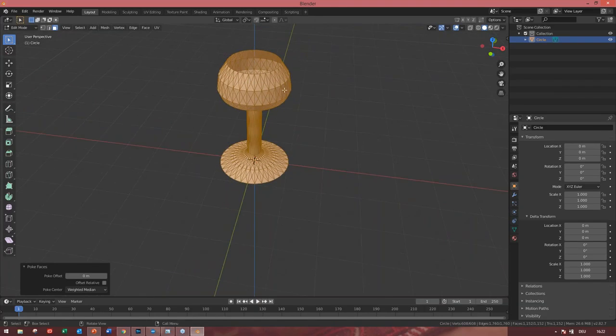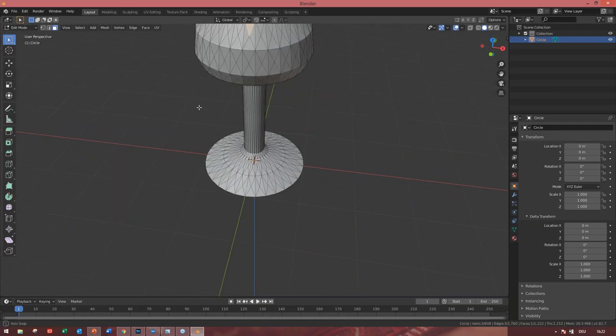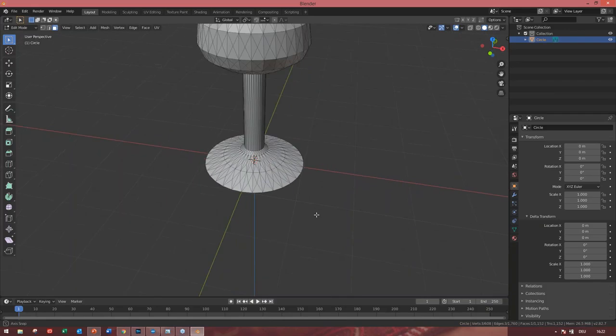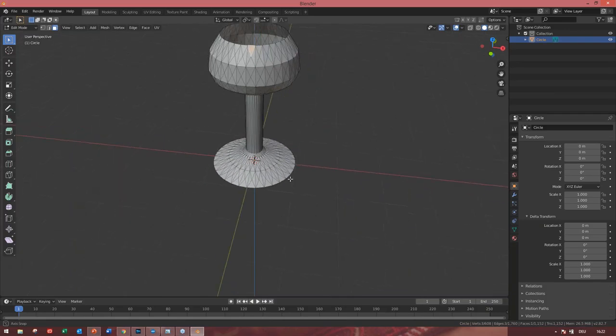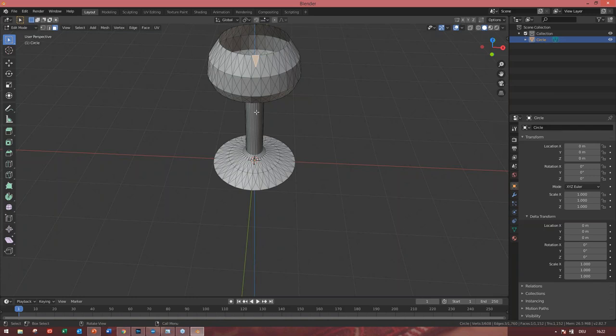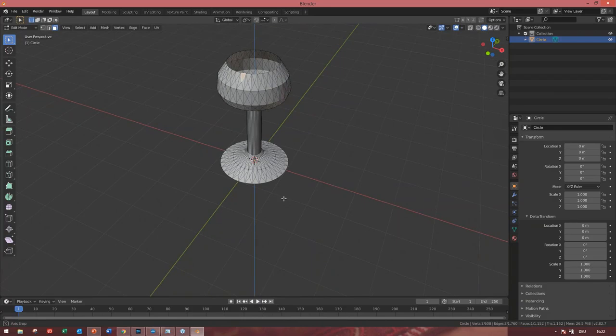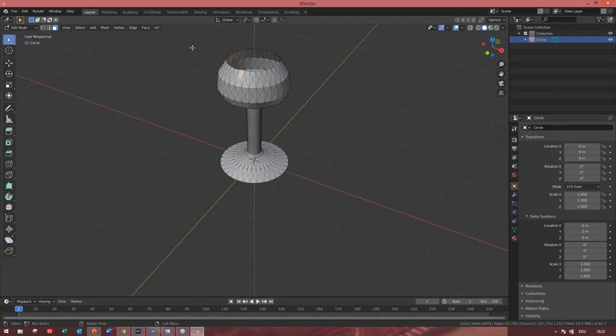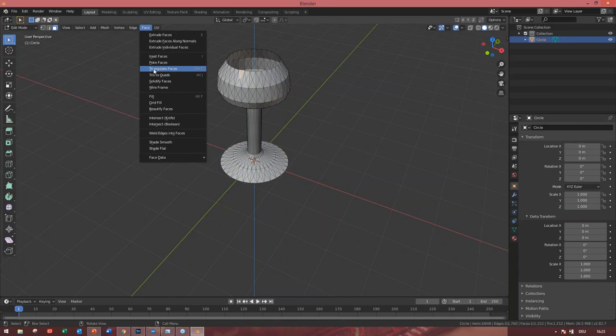That's also possible, and that will also work because we will have these single little faces in triangular form. But you will add a lot of vertices with this, so it's not needed to use Poke Faces for the Warper. If you want to save performance, use just the triangulate option for the triangular faces.